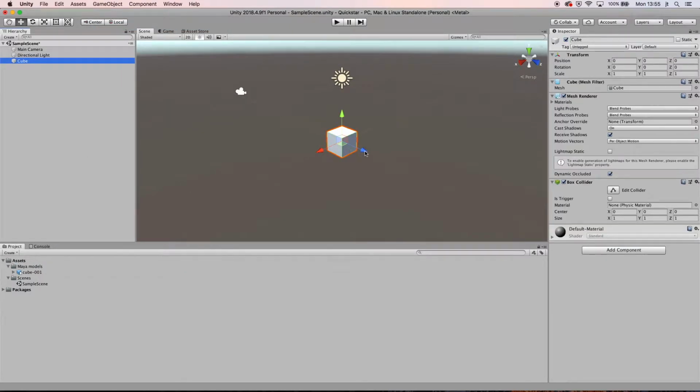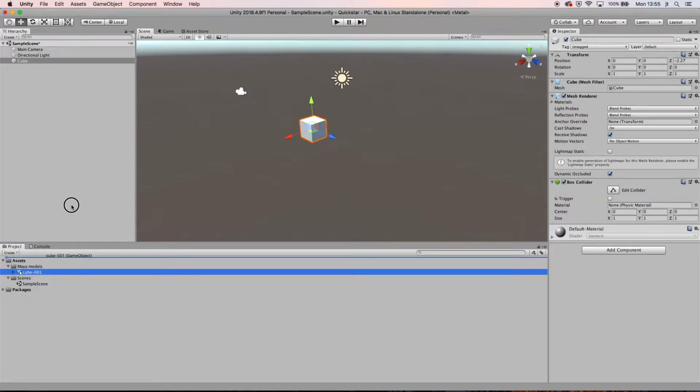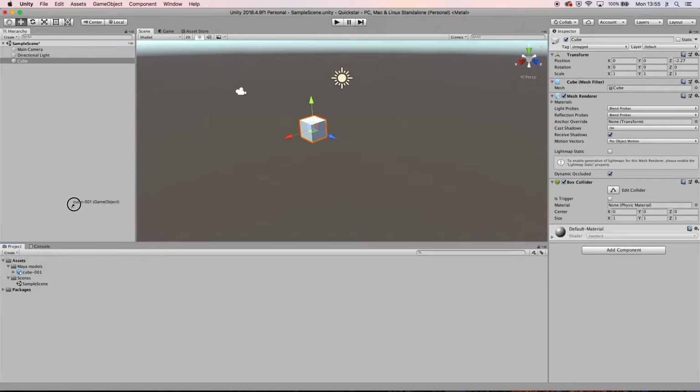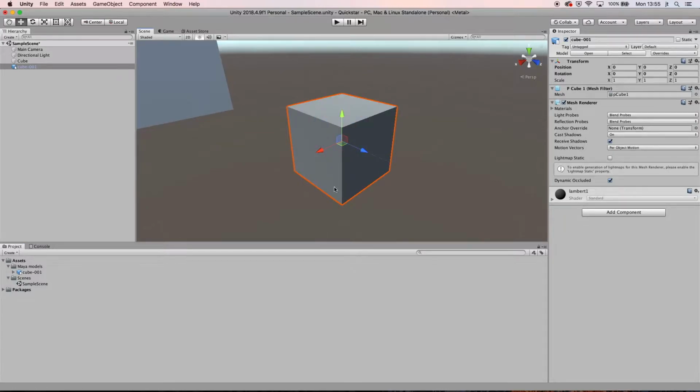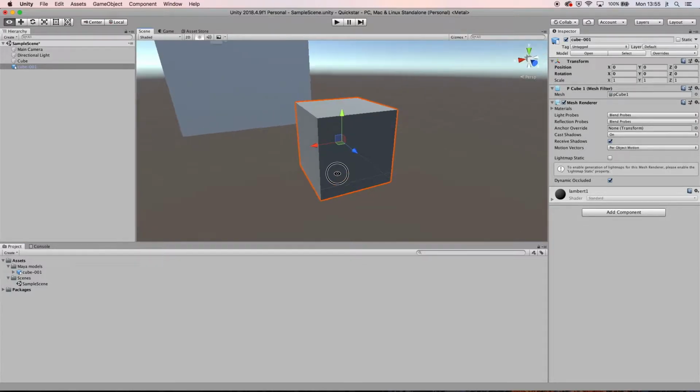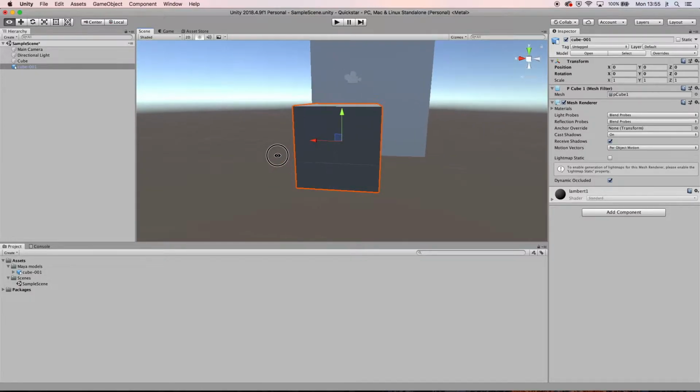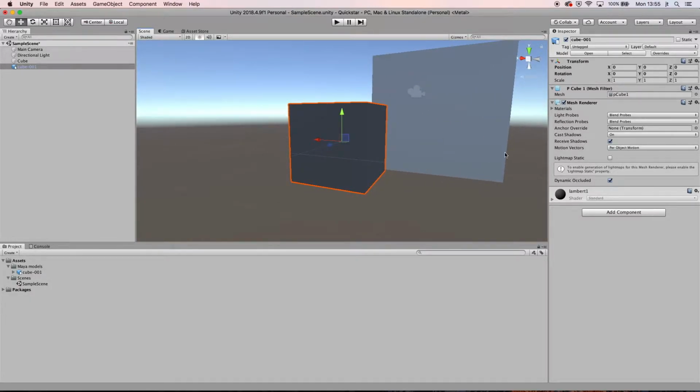The thing I really want to test is, is this the same size in Maya as it is in Unity? So I'll create a cube there. I am going to take the Move tool and move that to the side slightly, because when I drop in this cube, I want to be able to see both at once. So I'm going to drag this cube from the project window into the hierarchy, and I can see there actually isn't a cube there at all, but if I press F on the keyboard while I have that selected, I can see that it's come down very small. Now this is because Maya has centimeters as a unit and Unity is working in meters.